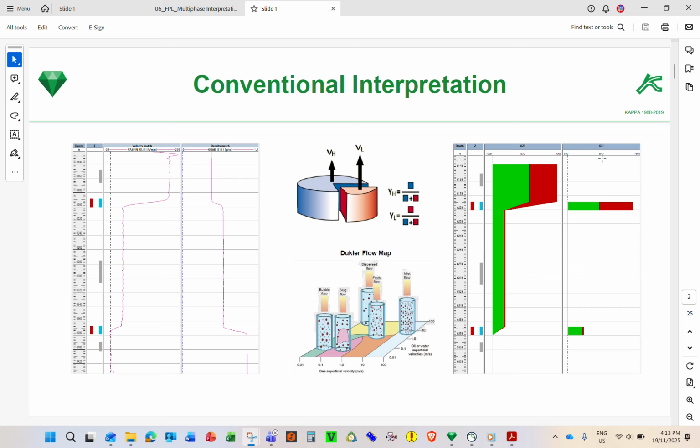You set the oil, right? Okay, so the slip rate will be calculated depending on the correlation we choose, and we end up with the Q oil and Q gas for different zones. So we try to match the total velocity from the spinner, the slip rate from the correlation, and the holdup calculated from density.